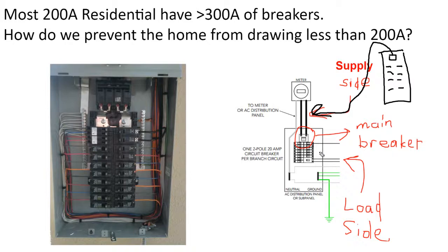But if simply offsetting the electric bill is the goal, easier project logistics can result from simply landing the solar array or the battery inverter or both at the bottom of the bus bar. A supply side connection requires a power shutdown from the utility. A load side connection does not.